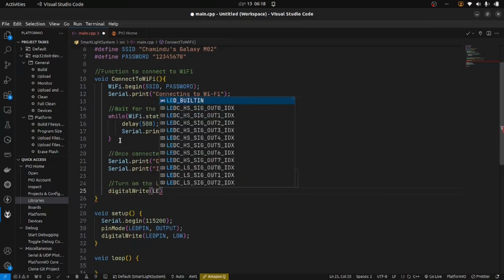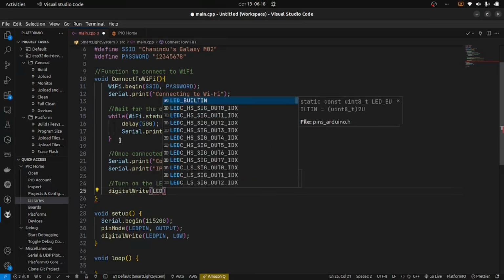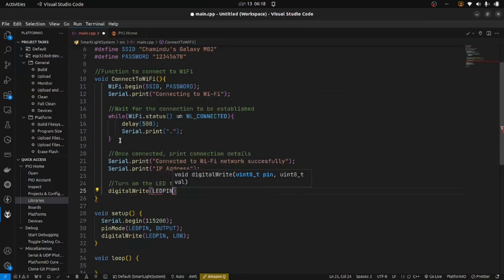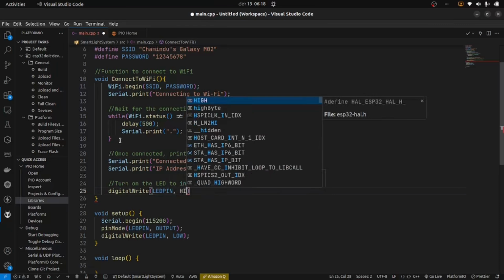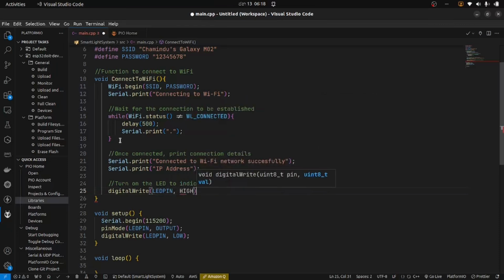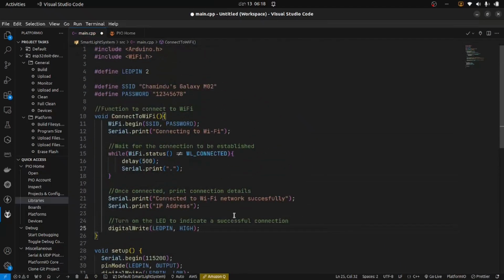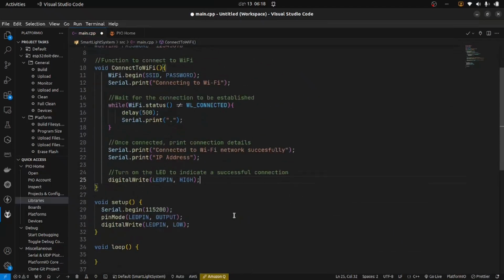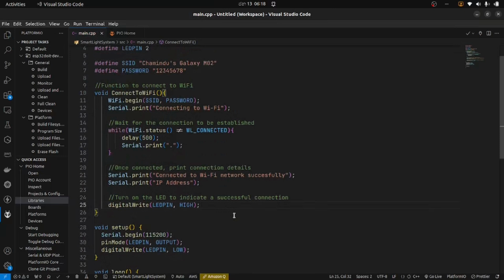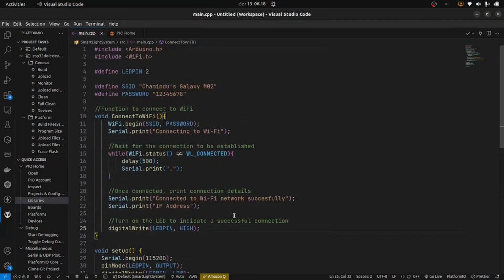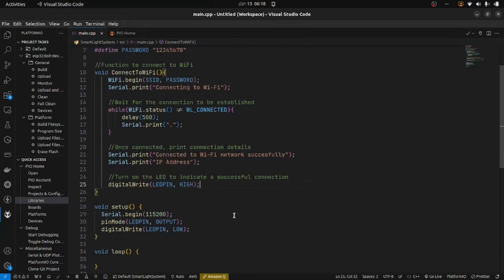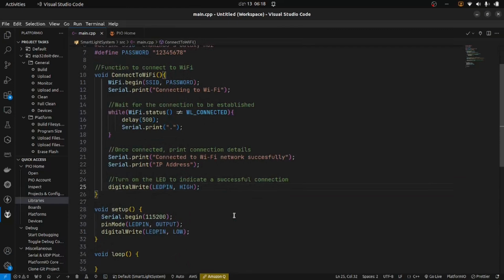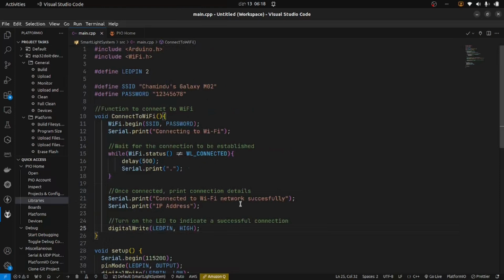So once the ESP32 board connects with the Wi-Fi network, it will turn on the LED. Here you need to change the SSID and password: the SSID as Wokwi-GUEST and the password as an empty string, right?